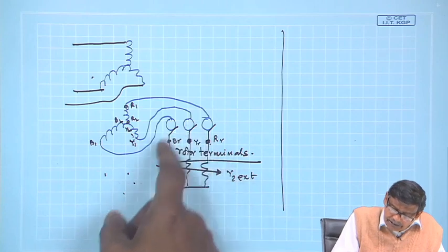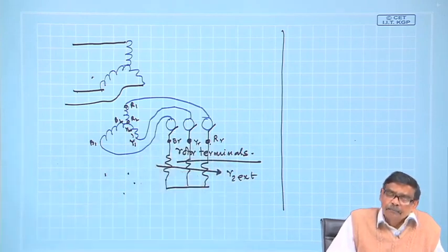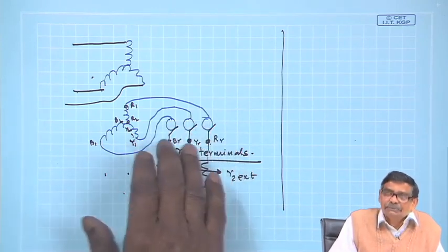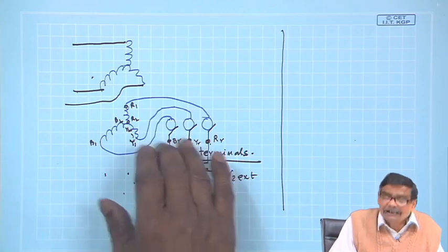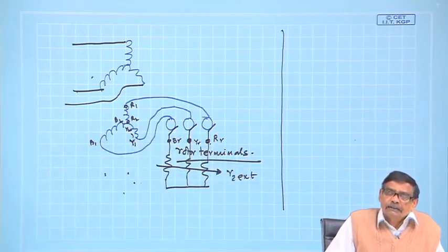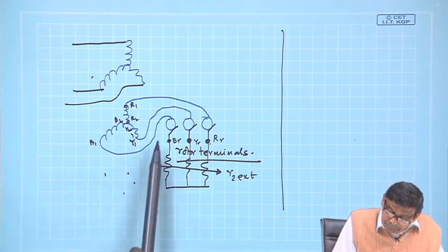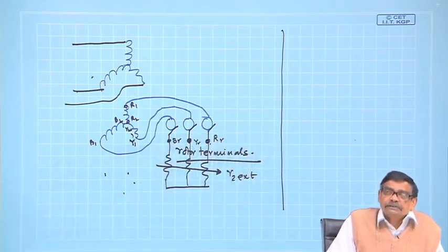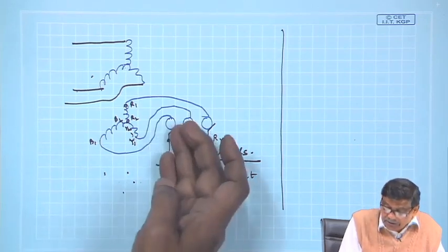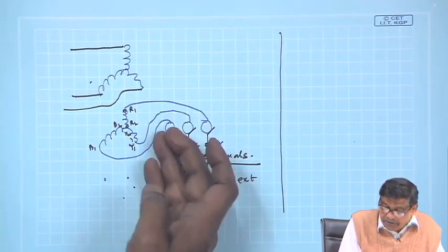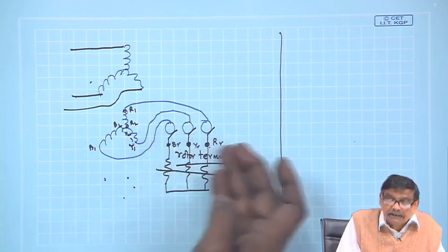While the slip ring and brush arrangement is a very nice one, it is also one of the things maintenance people won't like, because the brush has to be replaced during regular maintenance. The brush will wear out because of the friction between the copper ring and the brush.